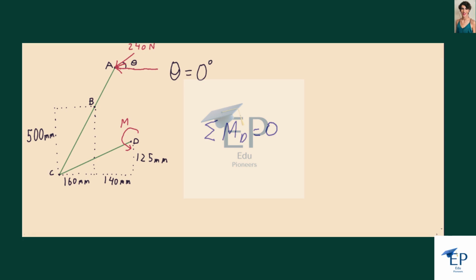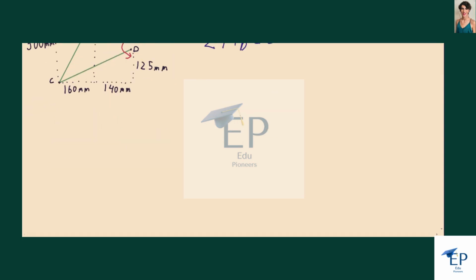So next we're going to solve for the x component of the force applied at C. Just by looking at the free body diagram, since there's only a horizontal force inputted, we know that there's also another horizontal force at C that's in the opposite direction. So we can say that the force, the x component at C, is equal to 240 newtons.